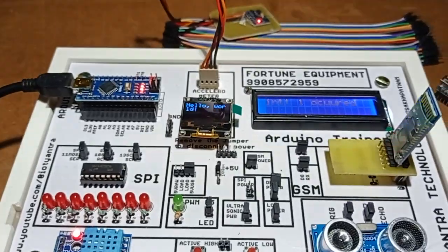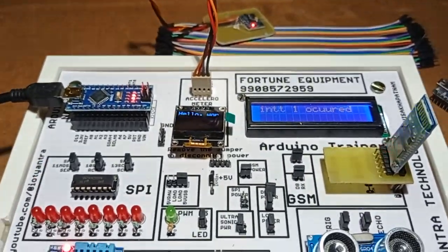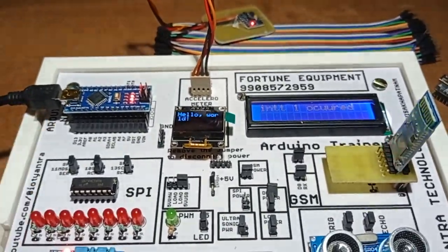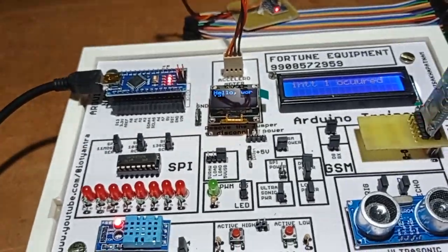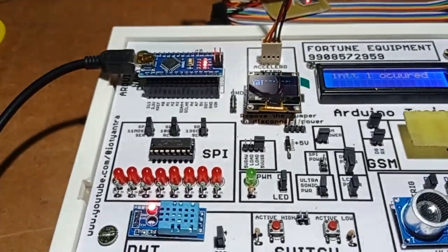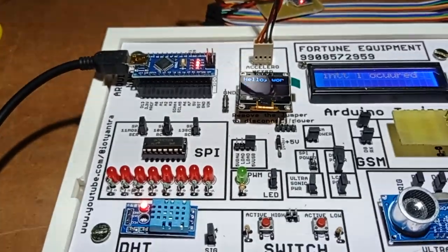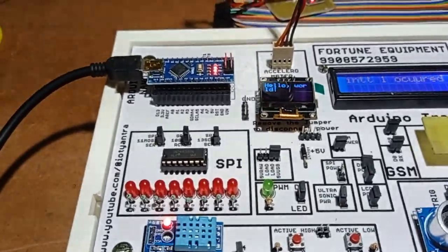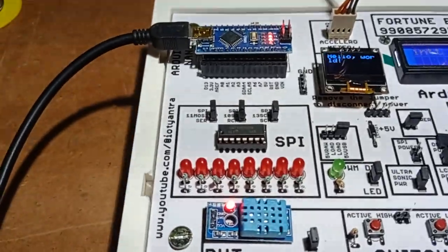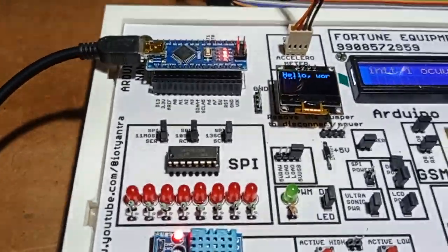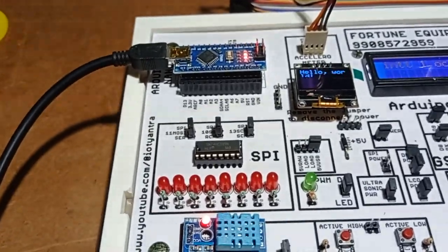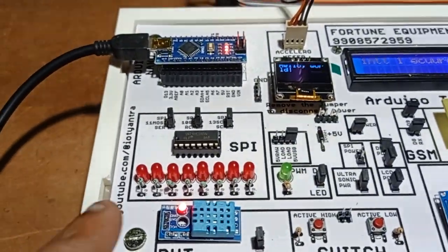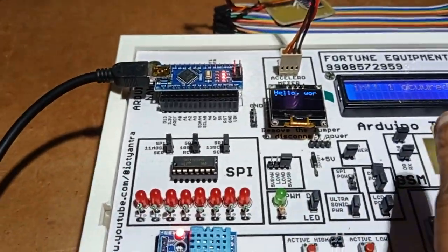So the clock is supplied by the master and the data will be transferred either from master to slave or slave to master only on the SDA line. So that is I2C. But in SPI there are two dedicated lines, master in slave out and master out slave in, MISO and MOSI. So there are separate lines for slaves to send data and separate lines for slaves to receive data. That is the basic difference between SPI and I2C.